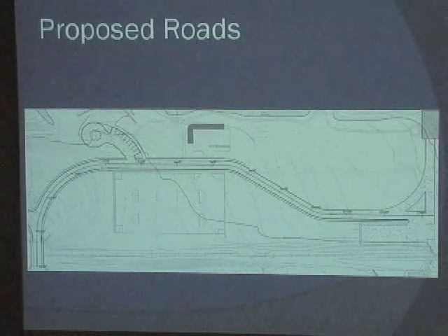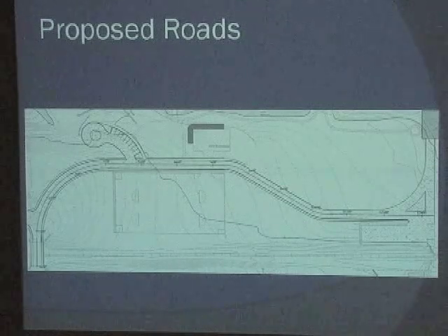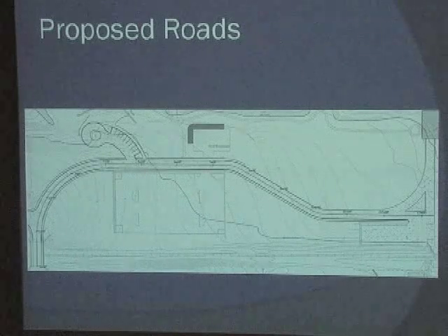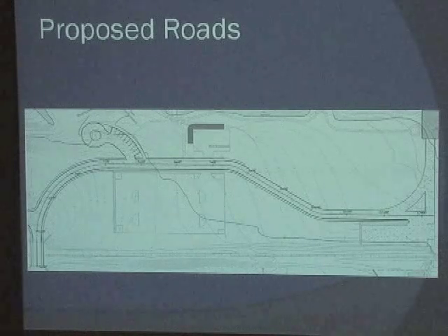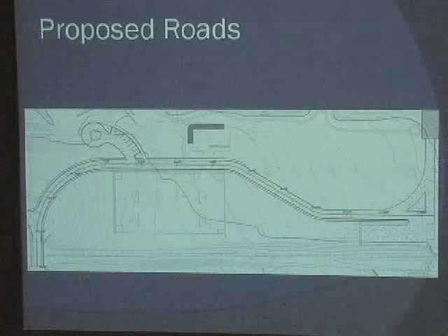emergency vehicles. It's over here. The entrance to the emergency road is located to the left after the bridge. It meets the minimum allowable turning radius of 30 feet. There will be a stop sign located on the emergency access road over here. And there's also a stop sign over here for the residents' parking.